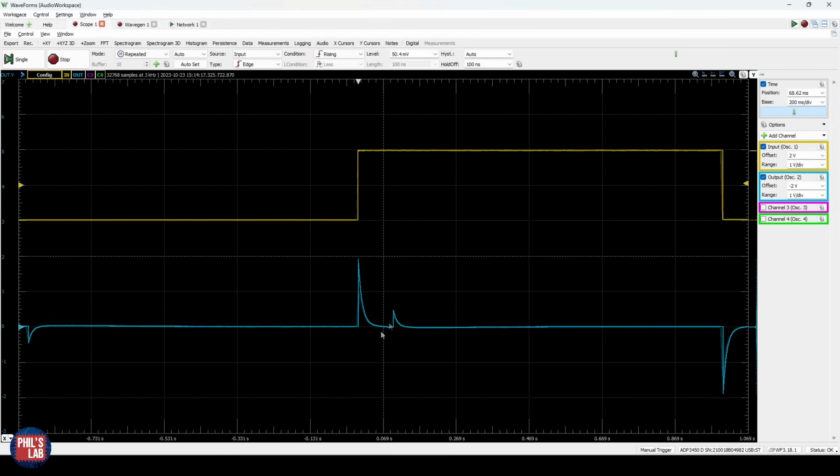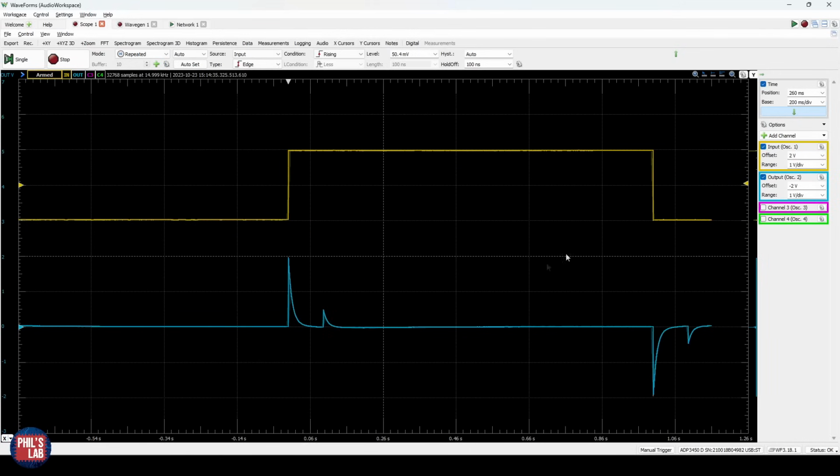which is what we expect in this case, because 0.8 is our alpha gain, which is our direct feed-through gain, which is happening directly on the transition, and then 100 milliseconds later, we're getting 0.2 times that original input signal, so that's why this is a smaller bump, and we get this for positive and negative going transitions in this case as well, just to show that alpha and beta control the pass-through gain, so to speak, and the delay gain.